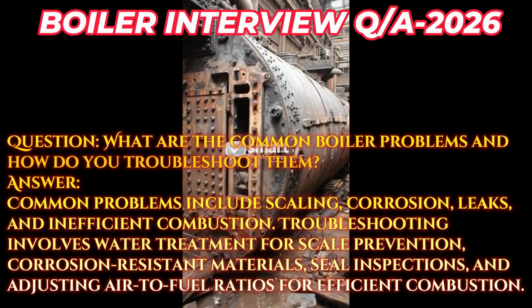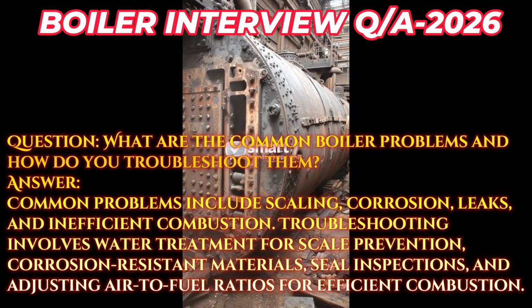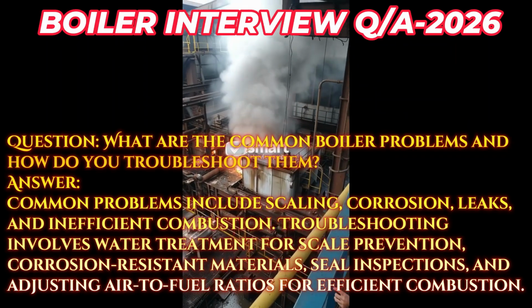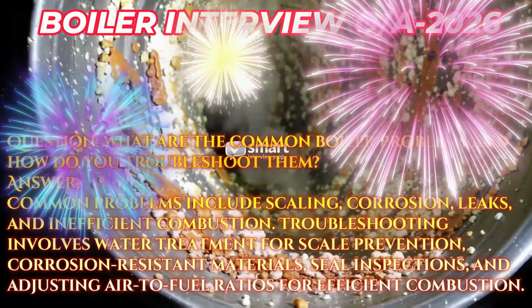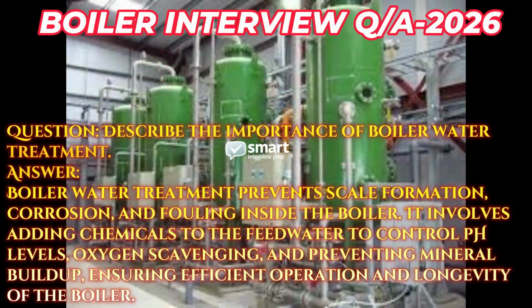Answer. Common problems include scaling, corrosion, leaks, and inefficient combustion. Troubleshooting involves water treatment for scale prevention, corrosion-resistant materials, seal inspections, and adjusting air-to-fuel ratios for efficient combustion. Question. Describe the importance of boiler water treatment.